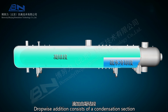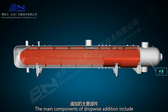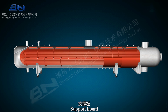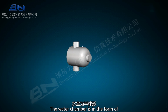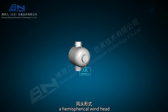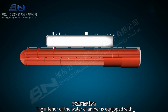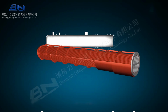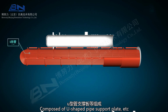The high-pressure heater consists of a condensation section and a drain cooling section. The main components include the tube system, support plates, and protective plates for the tube. The water chamber is in the form of a hemispherical head and equipped with maintenance manholes. The interior of the water chamber is equipped with a partition, a tube plate, U-shaped pipe support plates, etc.